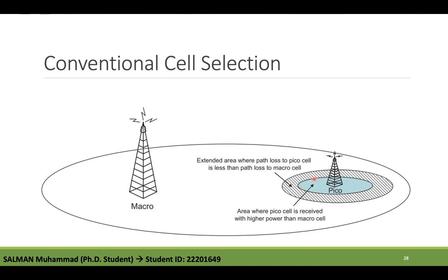Selecting the cell in which the path loss is the smallest, thus applying range extension, will maximize the uplink received power or SNR, thus maximizing the achievable uplink data rates. Alternatively, for a given target received power and terminal transmit power, the interference to other cells would be reduced, leading to higher overall uplink system efficiency. Also, it could allow for the same downlink physical resources to be used in other picocells, thus also improving downlink system efficiency.